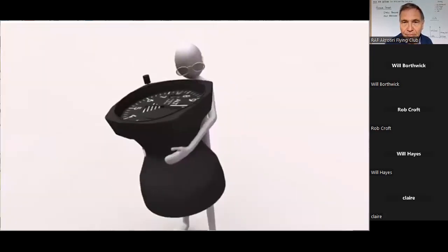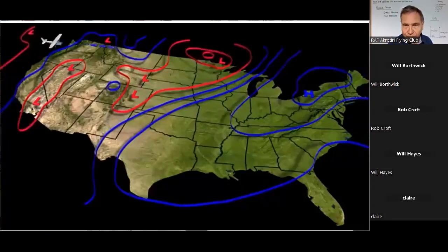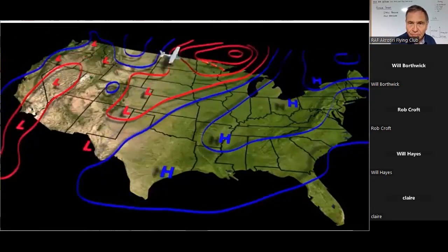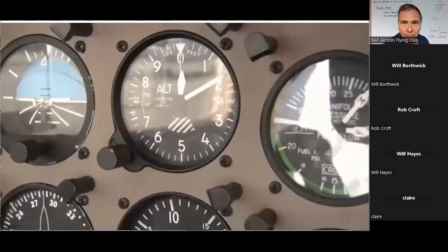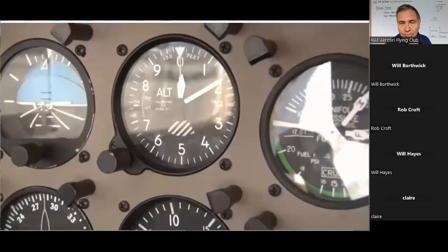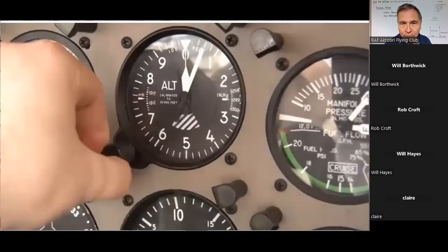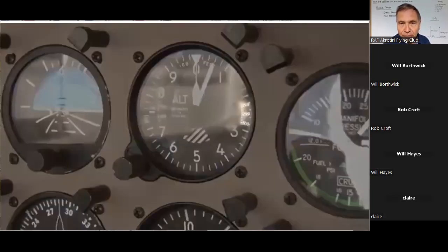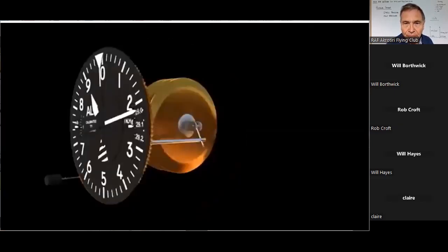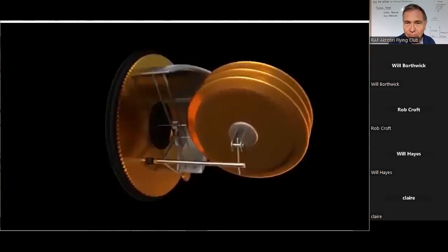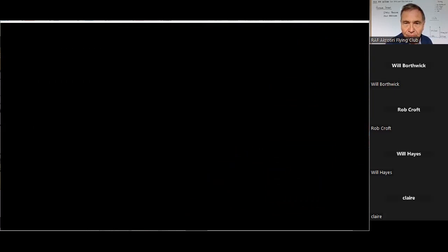This altimeter is actually called a sensitive altimeter, not because you have to hug it every once in a while, but because it can be adjusted for the current atmospheric pressure. Because the pressure at any given point on the Earth never stays the same, altimeters would always read incorrectly. Fortunately, pilots can correct this issue. Once the pilot knows the current atmospheric pressure, also known as the altimeter setting, all they have to do is rotate the dial on the lower left side of the instrument until the current pressure is selected in a little window on the face, called the Kollsman window. This then realigns the gears inside and the instrument reads accurately. The realignment is accomplished by rotating the entire inside mechanics of the instrument.